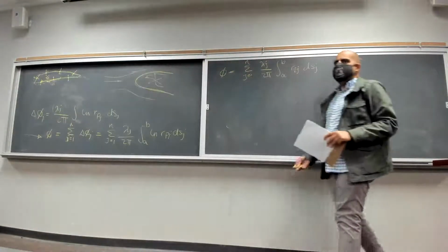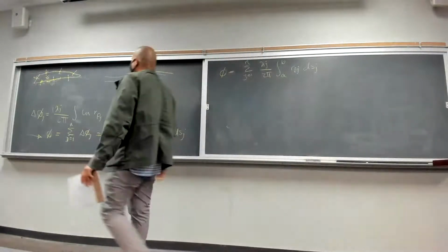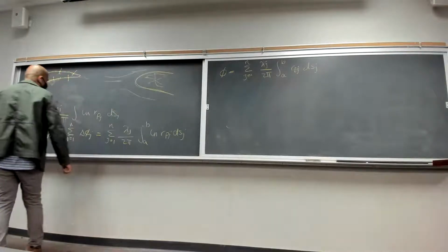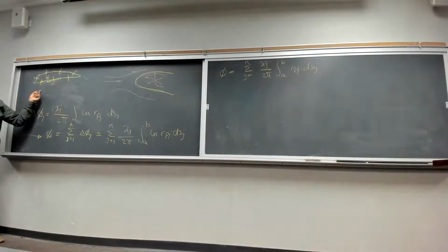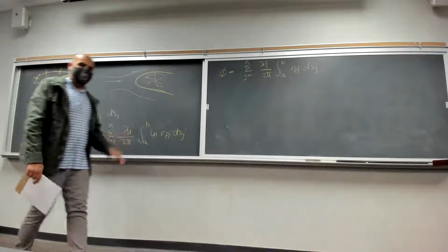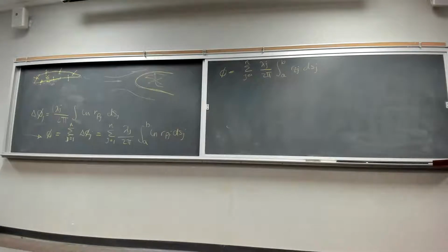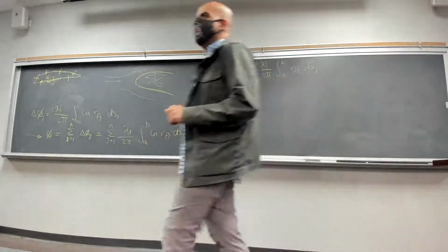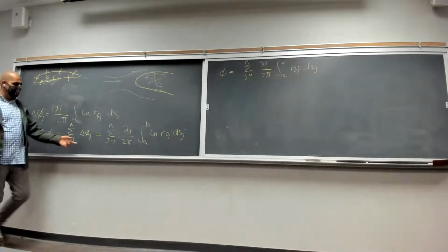Are there any questions so far? That's the velocity potential induced by one panel J on the panel I. Okay, and since we are taking the sum, this is essentially the velocity potential induced by all panels on one of the panels, on one panel I. If you're confused or if you have a hard time understanding this, please stop me. Yes. Two random panels, so it can be any two panels, right? And here, we are not moving panel I.